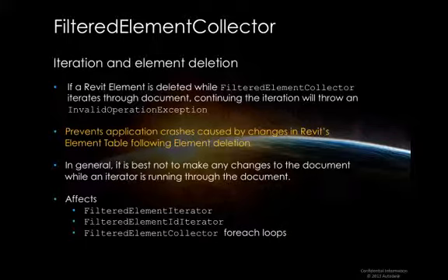That means that if you plan on deleting or even just modifying your elements in any way, the best approach is to first iterate over the document, create a collection of the elements you wish to modify, finish the iteration, and then go over your collection and perform the action that you desire. This action will normally require a transaction, and if you split the whole operation up into these two steps, you can actually perform the iteration first before even opening the transaction. That will clean up your code significantly.